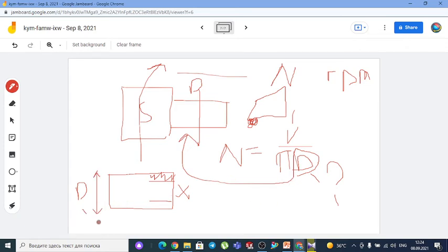You will take D as this biggest diameter here. Is it clear? What is D? Because it is important. In the case of milling, you take the diameter of the tool. In the case of turning, you take the diameter of the workpiece, the stock diameter before machining. I am speaking roughly.